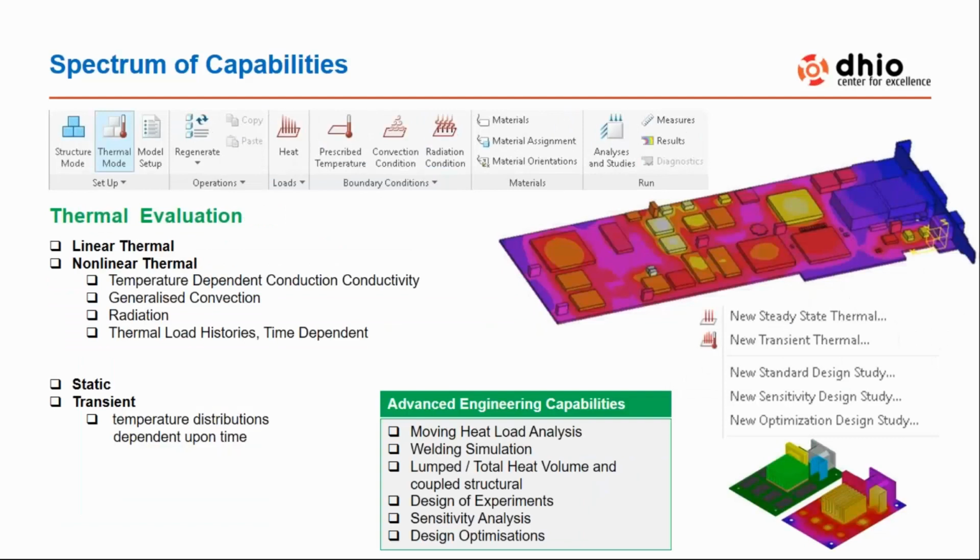And about the thermal evaluation, yes, of course, we have linear thermal evaluation as well as non-linear thermal evaluation. You can do steady state as well as transient thermal. You can involve the heat, prescribed temperatures, convection, all kinds of boundary conditions are possible. And there is an option where you can couple the thermal analysis with the static analysis, which is a very advanced thing that can be performed here.